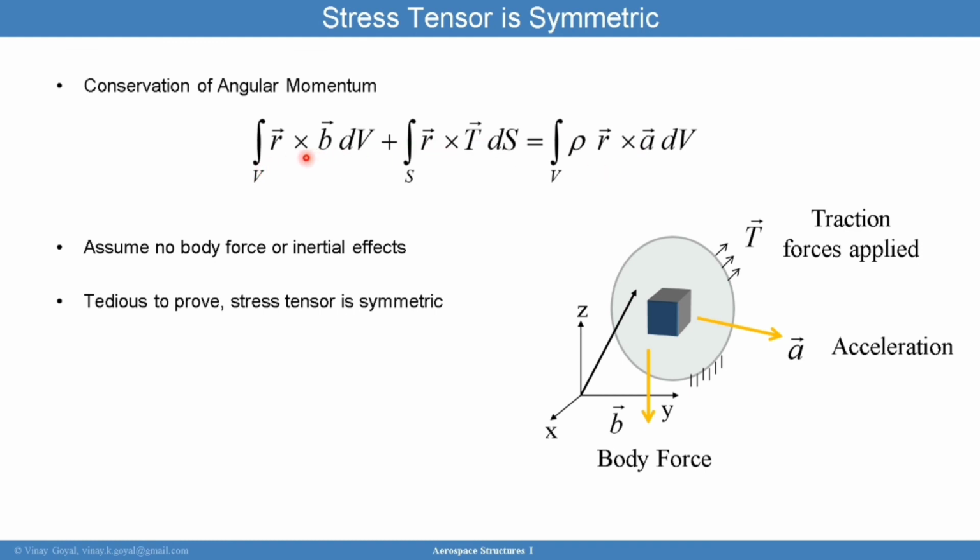If you recall from statics and physics, r cross a force gives me a moment. So I'm actually doing a summation of this r cross body force, which is per unit volume. So I have a bunch of unit volumes, and the body force is applied to each of these unit volumes of material, and I'm incrementally adding them all up, which is the reason I have that integral.